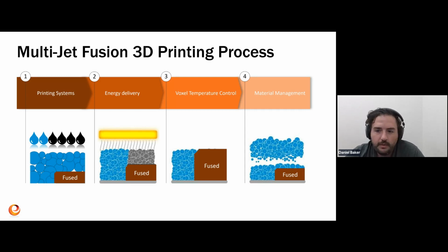From there, you have a Z-stage retraction. So your part actually goes down into the print bed. So you're not building up, you're building in reverse downward. The printed part also moves down with that bed of powder. And then finally, if you look at number 4, a new fresh layer of powder is deposited on top of that, and the process is then repeated.